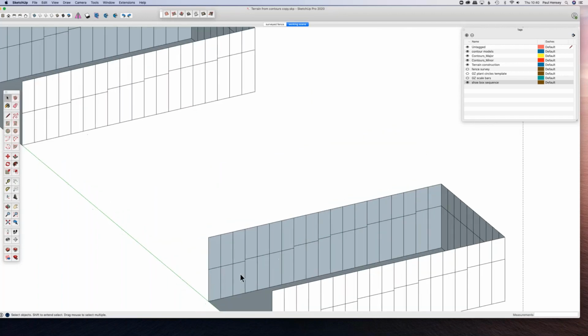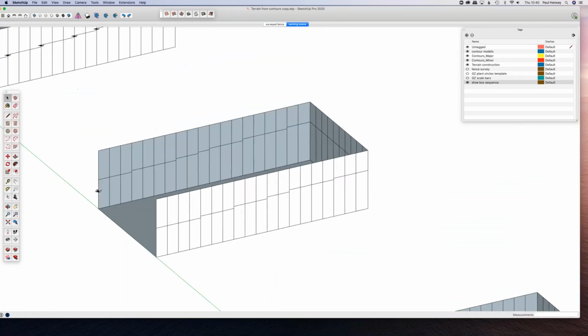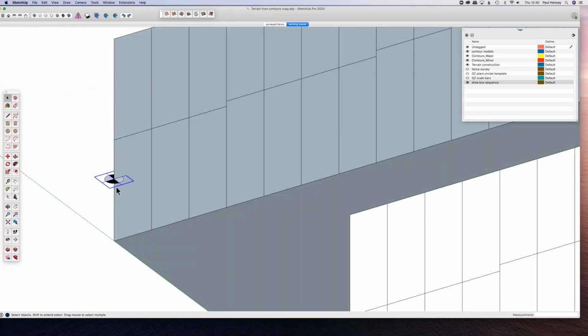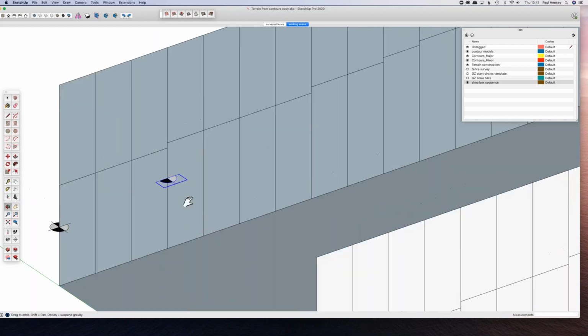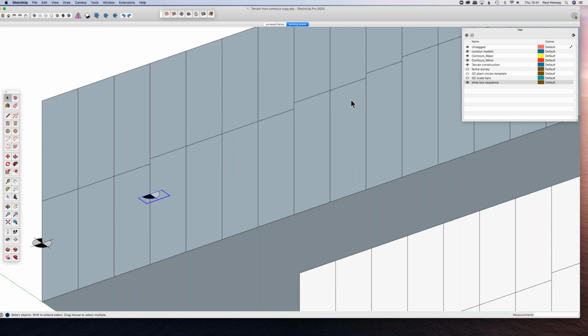And then you're going to measure down and record the position of the ground. And I use a little symbol like this, and I simply create this or have it in a library, and I bring it in to position. So it's at the top of the fence panel, and then I know what my offset to the ground is. So let's say it's 2.1 meters. And then I take a copy of this, put it in position at the next one, and drag the next one down. And I go around and look at my little survey drawing and reference each of the positions that I've marked and put one of these circles in place.